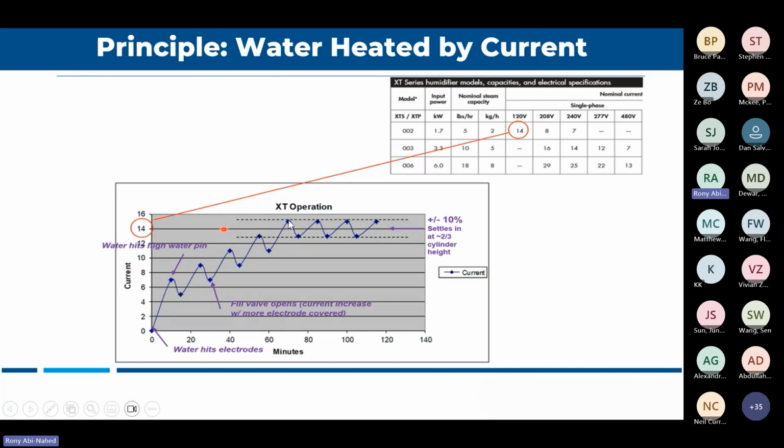And then will always operate plus or minus 10% the whole time. So where this application makes sense, first, as I said, depending on the water quality, if you have the ideal range of water quality, it's fine. And for comfort application, where a human being doesn't feel the difference between 40% or 45 or 50% relative humidity. So that's where it can make sense.